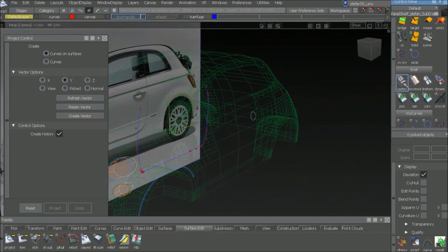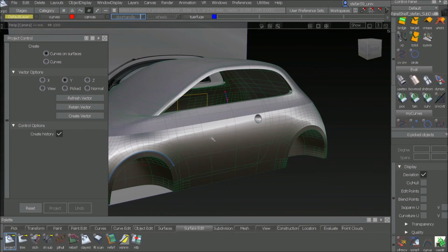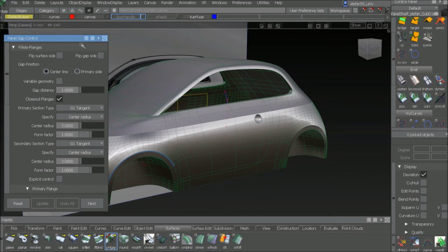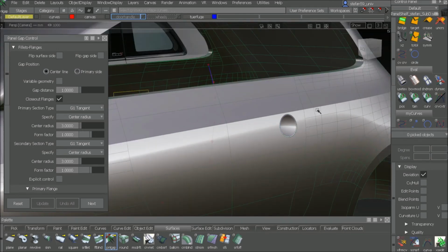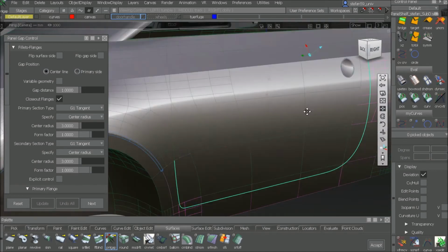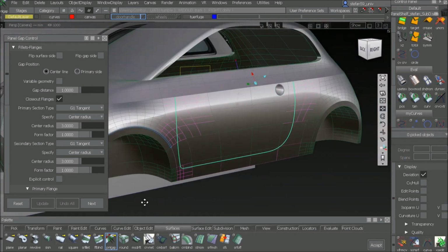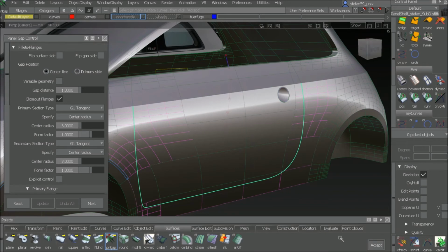On these curve and surfs, I can drive a panel gap. Panel gap is very complex, so this time I do it the other way around. I first let it run through this panel gap command, and then I explain what values you need to have a successful panel gap. So I go there, identify the curve and surf on this first part. So keep in mind we have a sharp edge. So below the sharp edge, it runs along and it finds it here. Click again to continue. So now we have the complete path for the panel gap, and I accept it.